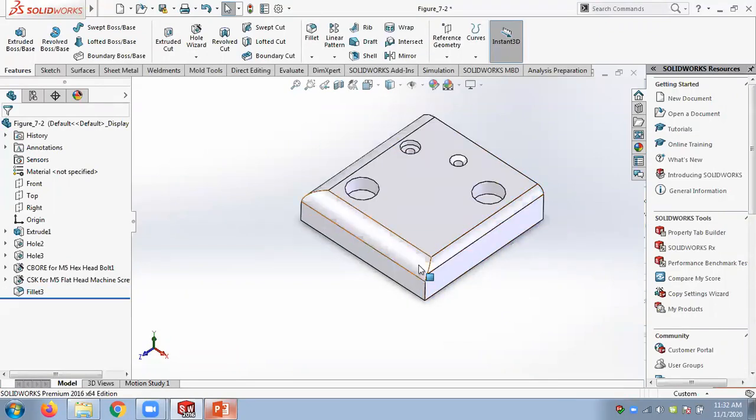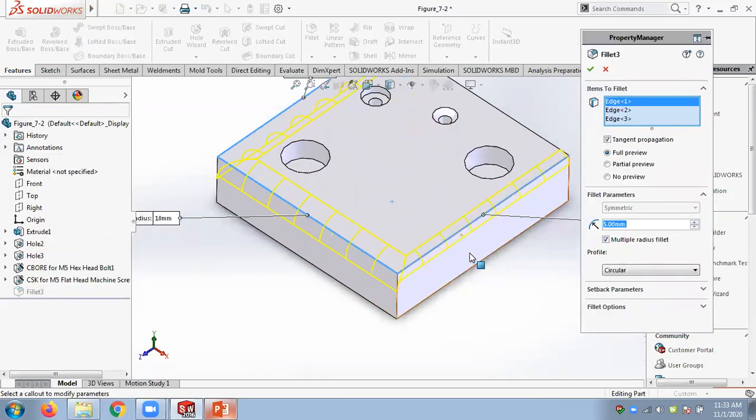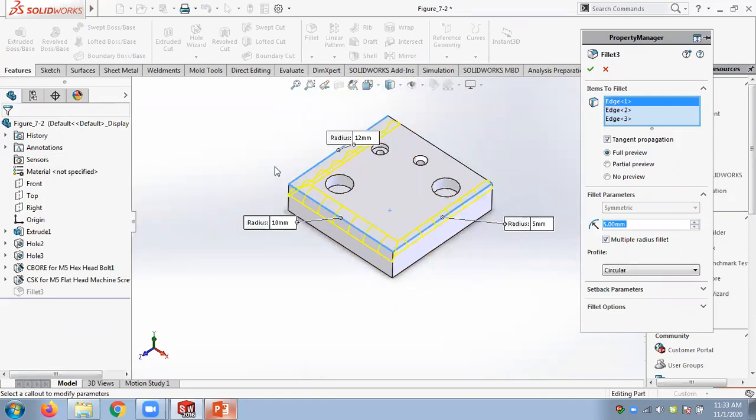Normally we don't practice these kind of designs. These are irregular shapes. Manufacturing wise also difficult, so we will not do that. If you look at your mobile phone, everywhere the same fillet radius is there. So we don't try to have different values in different places, which is going to be difficult in manufacturing. Better you put full preview on, then you can see it. Otherwise, you may not see the correct output.